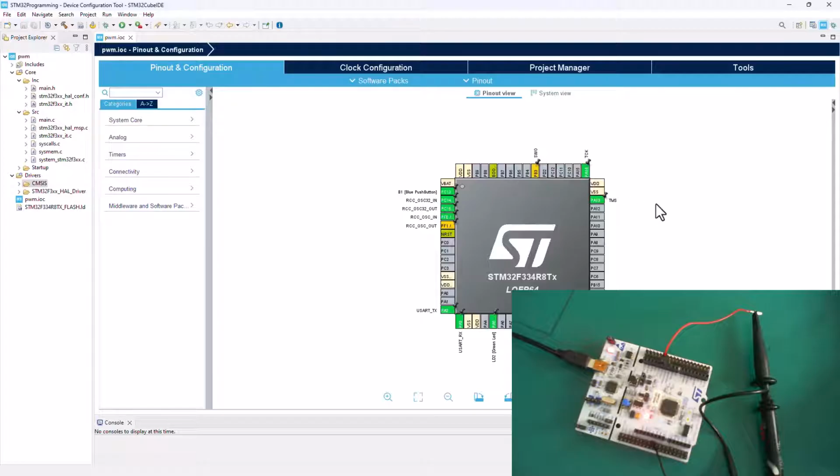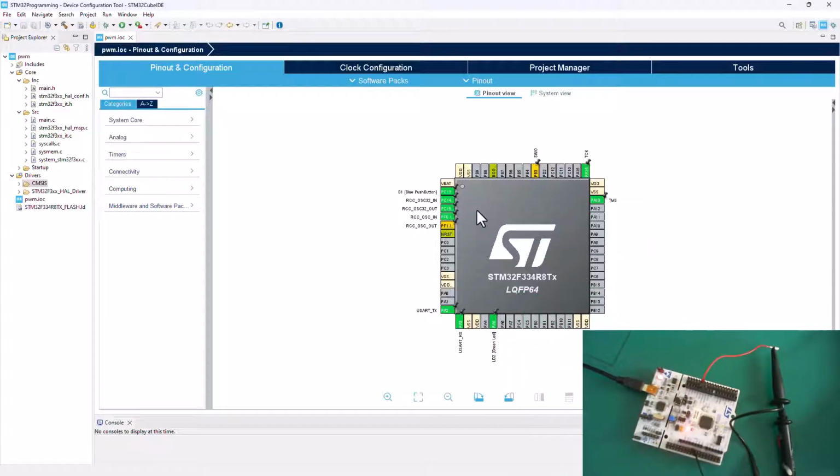So what I'm going to do here is, right now all of these are going to be generating a lot of stuff here, which we don't need for what we want to do. So I'm going to go ahead and just reset this. Actually, I'm going to reset it because we're going to use the internal clock frequency, not the external one. So we don't need this RCC OSC out. Those are basically designed for the external oscillator here.